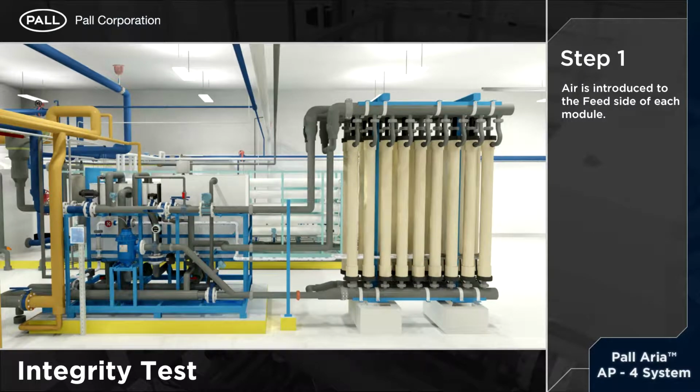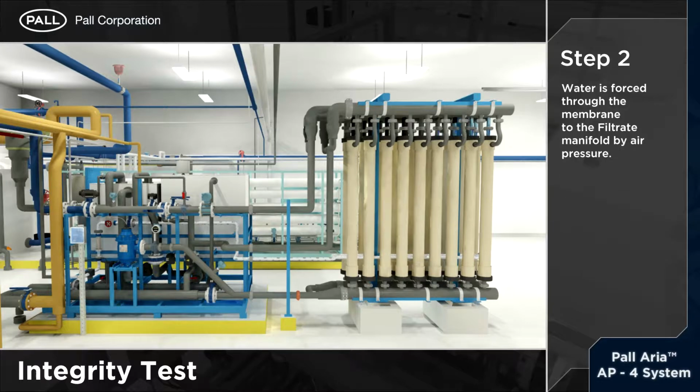In the daily integrity test, air is introduced to the feed side of each module. Water is then forced through the membrane to the filtrate manifold by air pressure. Note that the air is unable to pass through the membrane fiber.